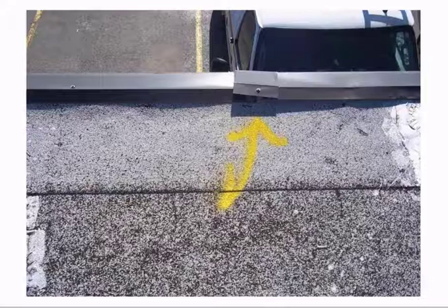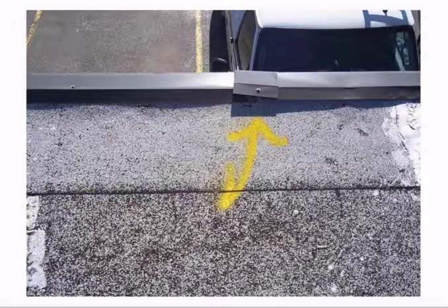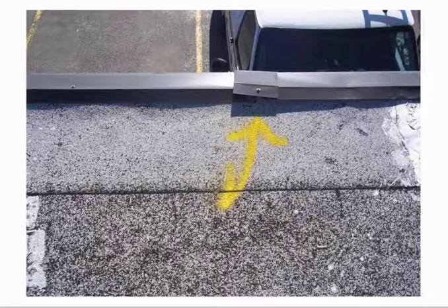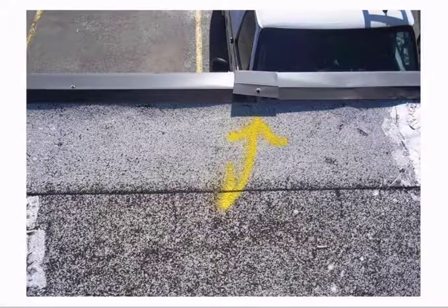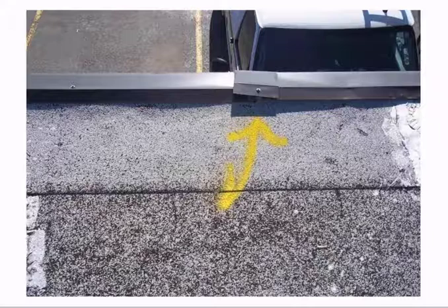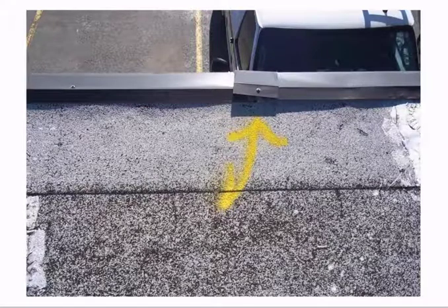Gotcha. What might you be able to do in a remedial scenario like this? You come into this situation, clearly that's going to be problematic, leaking. What are some things that you could do to make that a good, solid repair? Typically what I see is people just caulk the edge. To make that repair a little more long-term and durable is take that small piece off there and just put a larger piece on there, like a 2-foot piece minimum. And then you can fasten it back down.